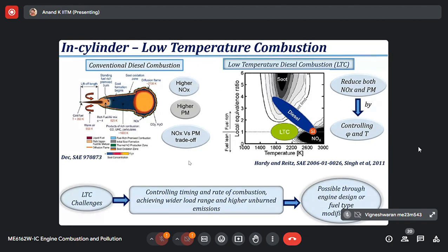Not GDI. It's gasoline with port injection. To create pre-mixing, I'm not injecting directly. I'm injecting gasoline in the port. So I can use a conventional port fuel injection system. Again, that is another advantage. You don't need a high pressure injection system. Sir, is your research aimed at whether a current diesel engine can be run with it? Yeah, that is what we have proven. A current diesel engine can run with a gasoline PFI system in this combustion mode, not in conventional mode. Okay. Got it.